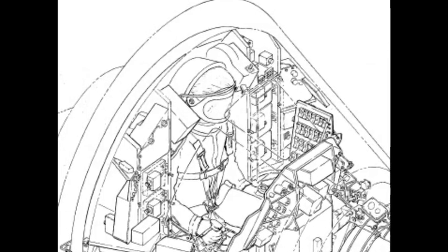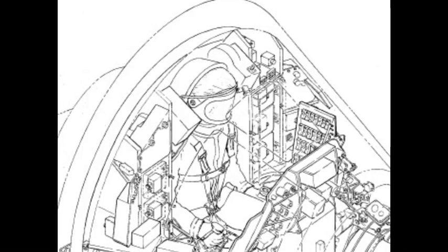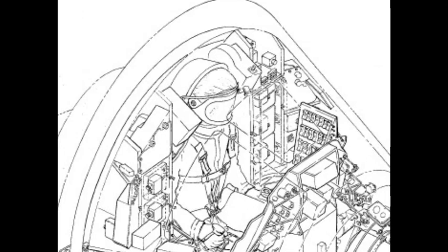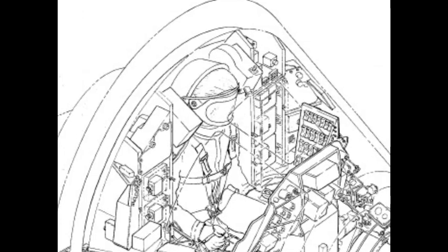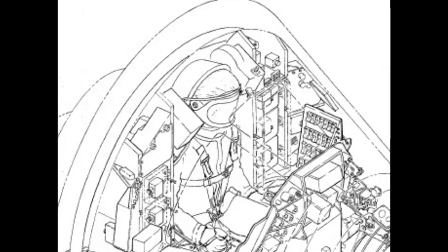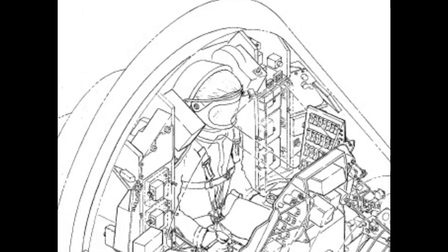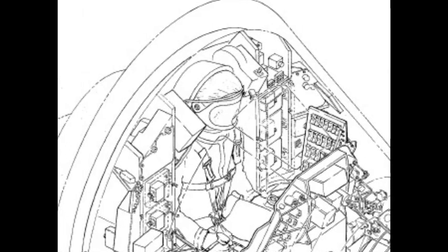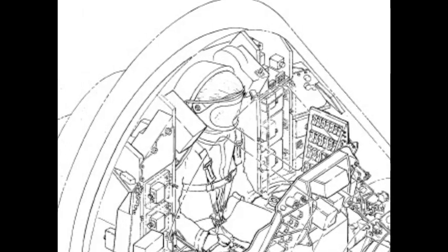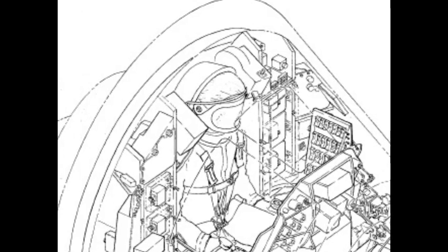225. Antenna fairing. Capsules 2, 3, and 4 antenna fairing destabilizing flaps are smaller and of a different shape than the specification capsule. See Figure 2.5. The antenna fairings also house a drogue chute that stabilizes the capsules during landing phase. The drogue chute is automatically deployed from the antenna fairing when the capsule has descended to 42,000 feet altitude.